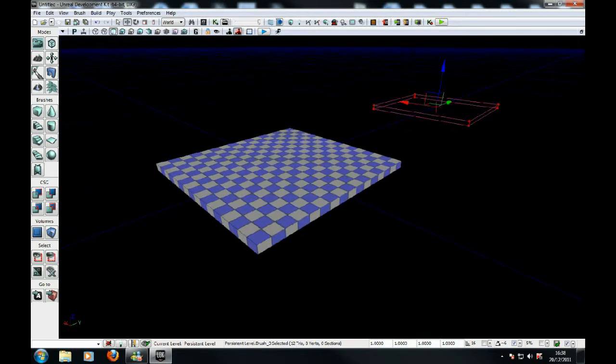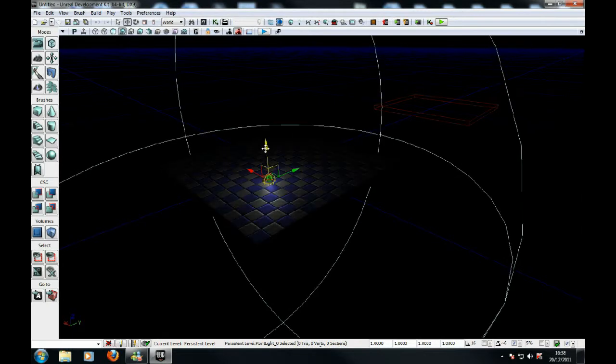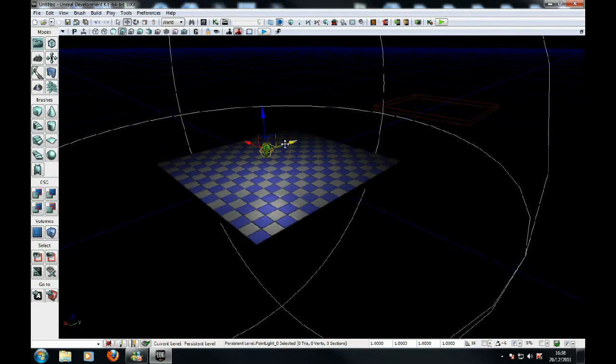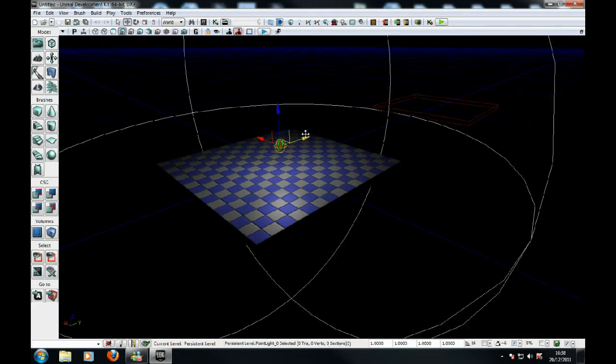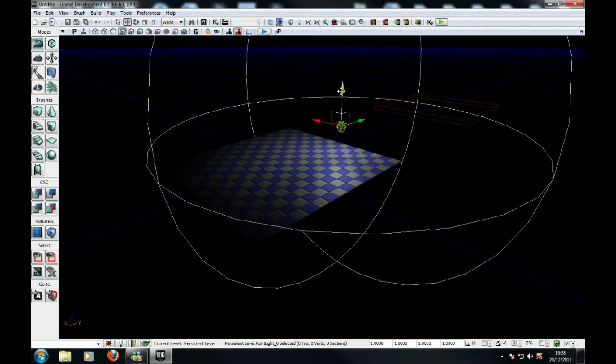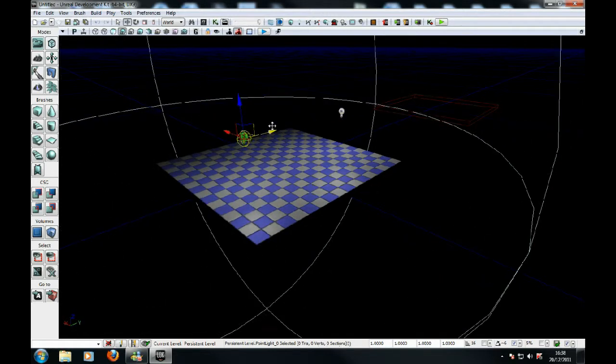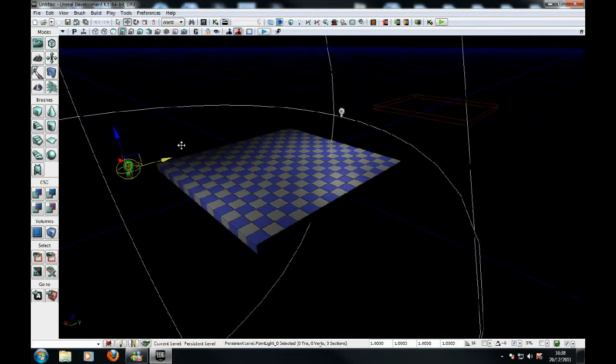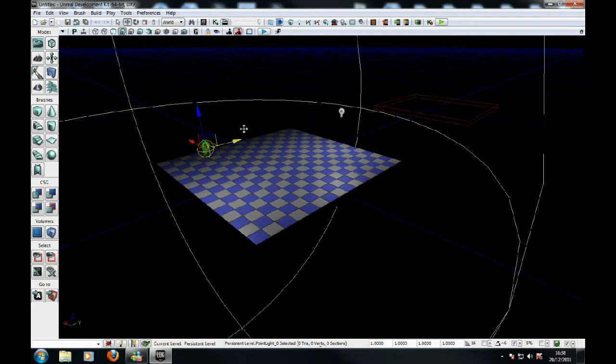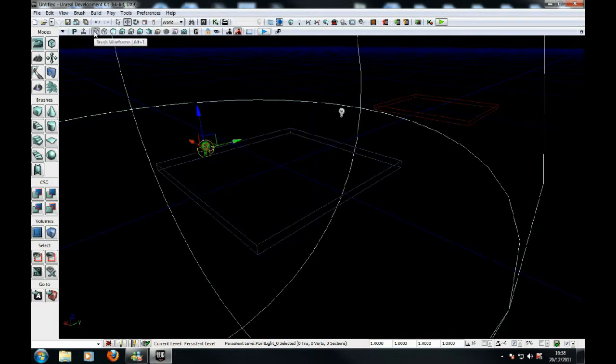It's on default lighting, so everywhere's lit. So we'll go on to normal lit, and as you can see there's no light. So hold L and left click, drag it up, and you've got yourself a light. And we'll have that here. Hold Alt and left click, and you can have another like this. If I go to wireframe, brush wireframe, you can see this BSP wireframe here.